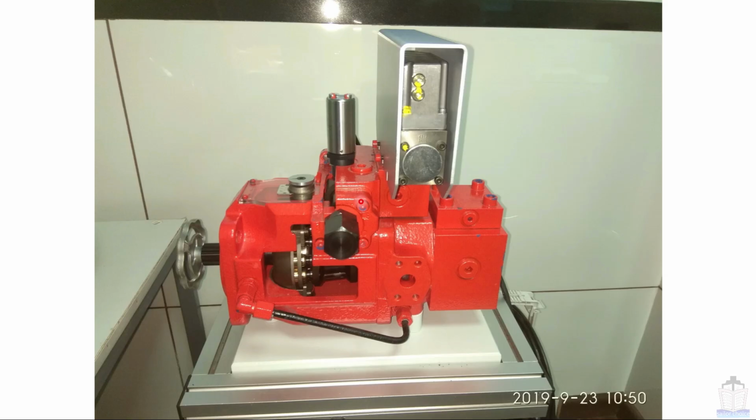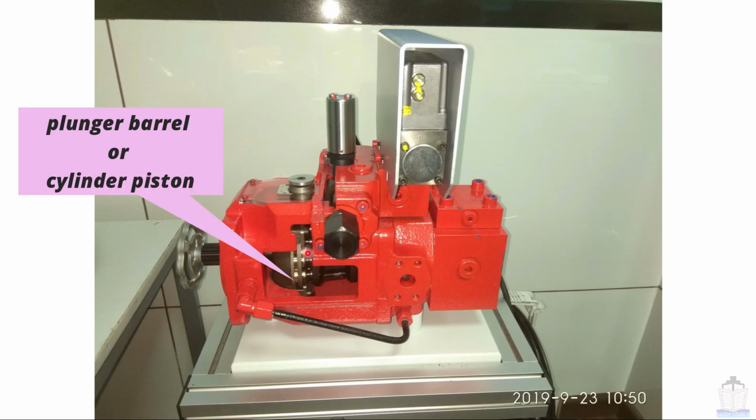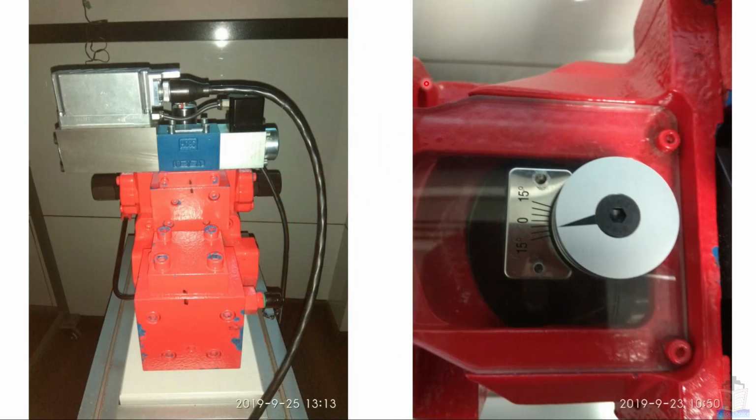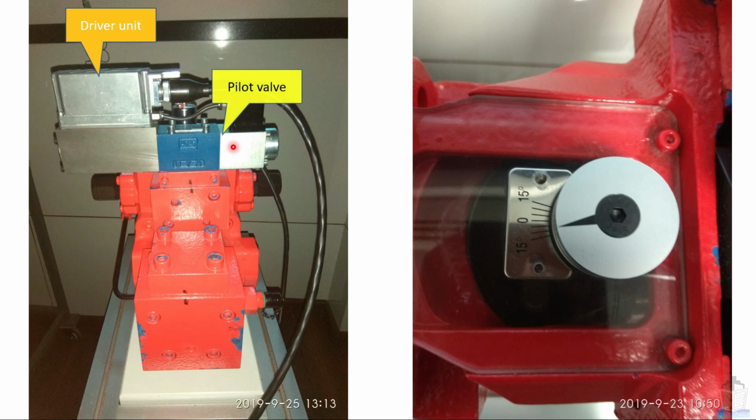This is the engine driven swash plate pump. Here in this area plunger and barrel are situated. This is a feedback unit for swash plate position indication, and this is the hydraulic control valve, also called the main valve. This is the pilot valve and this is the driver unit. Now let's have a look from a different angle. This is the driver unit, this is the pilot valve, and this is the angle indicator.